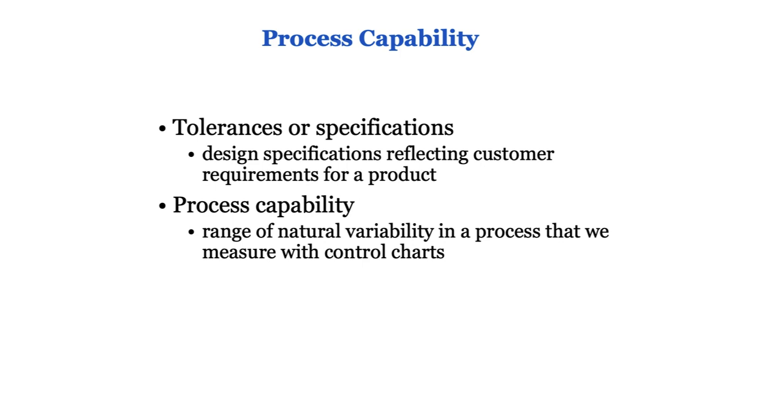It can increase or decrease gradually, which typically indicates fatigue on the part of the operators or wear and tear on a tool or machine. There can also be an abrupt and sustained increase or decrease in the sample mean, which is typical of a shift change or new employee or changing raw materials.